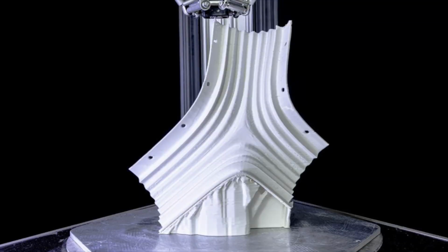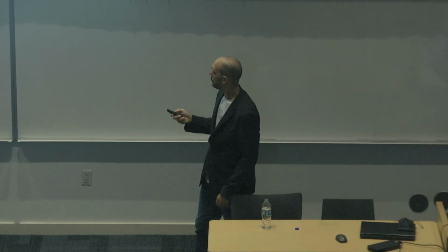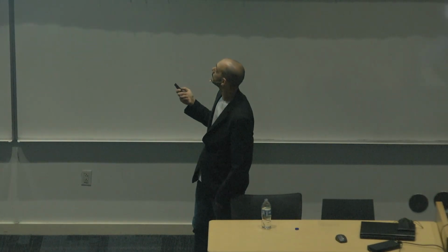Because when you pour the concrete, it starts to apply a lot of pressure and it starts cracking the shells. And we wanted to reduce the amount of material that we wanted to use for the formwork, so we were trying to reduce the material by achieving these corrugated surfaces that were kind of acting as reinforced surfaces.